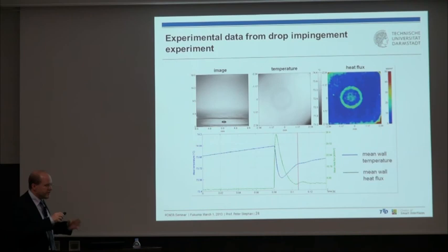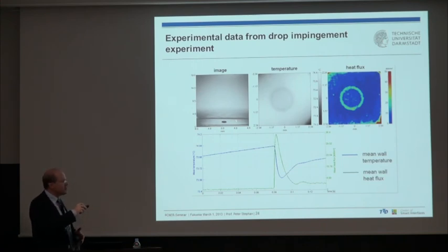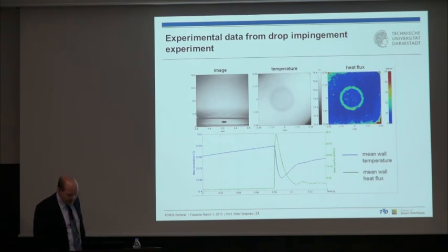And you also see here that the droplet first spreads, because you have high inertia forces when it hits the wall, depending on the initial velocity, and then surface tension becomes dominant. Then it moves into a droplet shape like this, depending on the static contact angle, and then it sits. It's a sessile droplet at the end on the wall, which partly evaporates and will disappear with time due to evaporation.